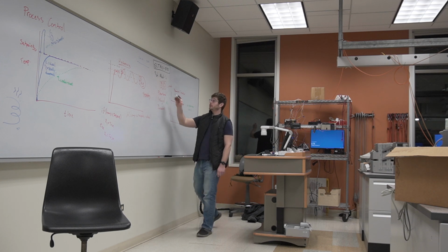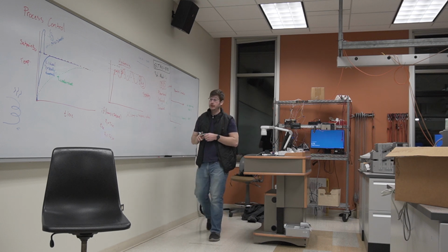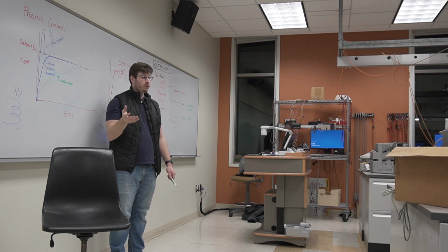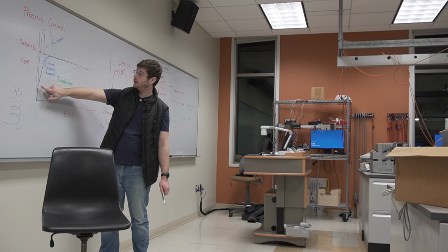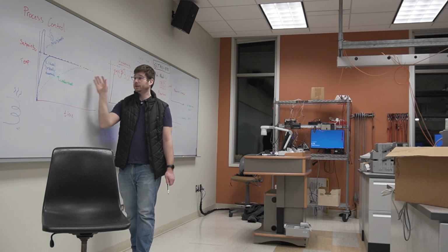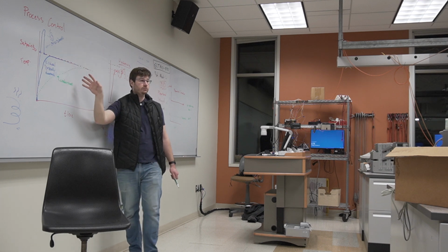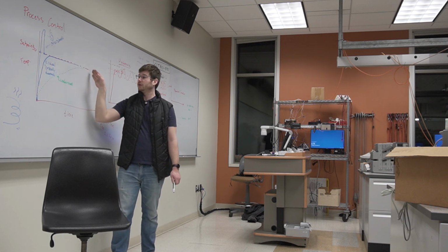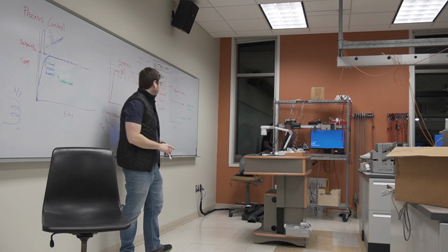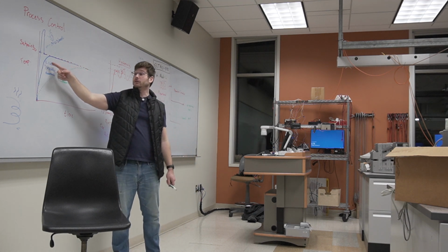All right, so P, I, and D can be tuned. So what that means is that we can change P, I, and D, which is typically between 0 and 1. We can tweak those values to try to get a curve that responds just like this in the ideal case, okay? So you can plot your process, you do a set point, and then you let it go and you see what happens and you get this chart and you see where on this chart you are. Are you undershooting or underdampened? Are you overshooting or overdampened, or are you ideal? And then you tweak your P, your I, and your D accordingly to try to get as close to this ideal line as you can.